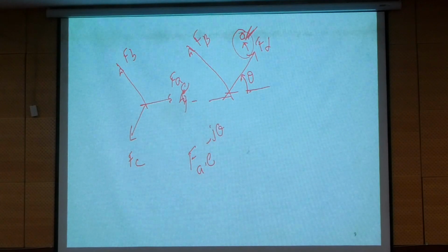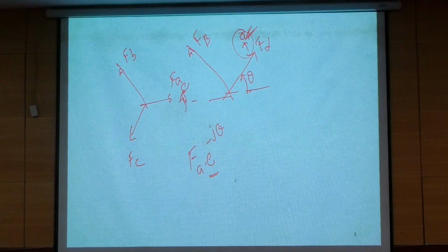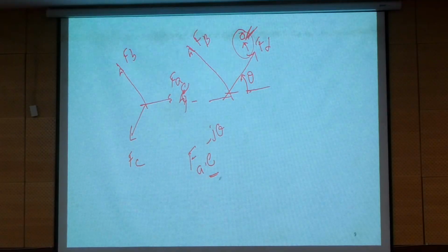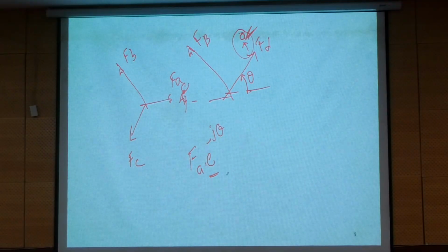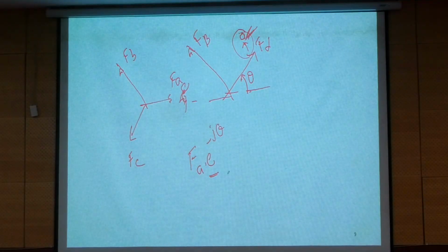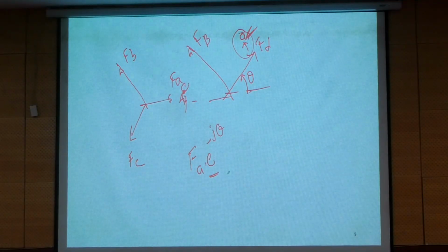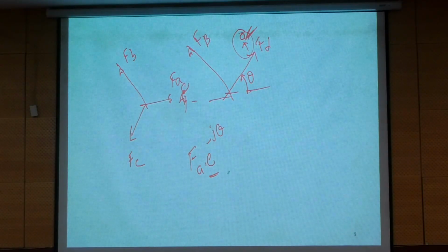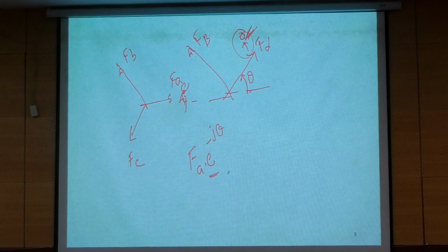You got my point? If you multiply FA with e power minus j theta, you will get clarity about the effect of FA on the reference person in the D axis as well as the Q axis. You will get clarity about the effect of FA on the alpha axis and beta axis if you multiply with e power j theta. Right? Next, what about FB?